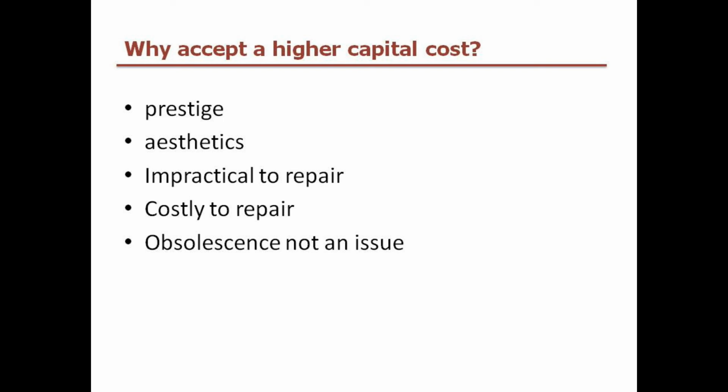But once you start looking at it from a life cycle perspective, there are many other issues as well: prestige, aesthetics, and practicalities in maintenance and repair. It's a big issue. You can spend a lot of money once we start moving out of that 10-year period with a building. All of a sudden things are not that new anymore, and some of those repairs, if there are chillers in wrong parts of the building, or if the building had a little bit better design with plant rooms and access to windows for cleaning, become costly to repair and maintain.